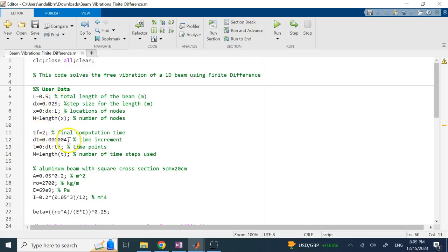And here I need to use a very small time step size. Otherwise, you will not get that parameter less than 1/2. So I only simulate for 2 seconds. You can go more; you have to wait more. And so you see here I'm using literally 4 microseconds.